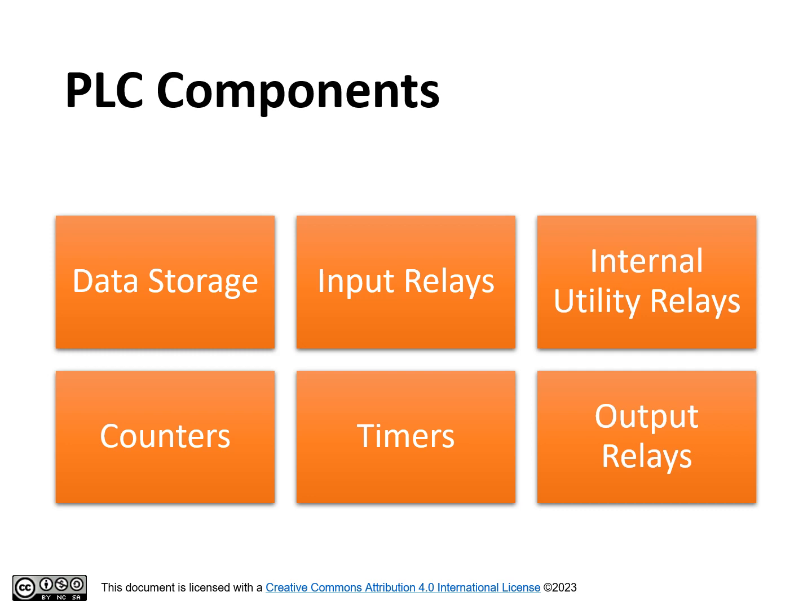Timers. These logical components come in a variety of types. They can be on delay, off delay, retentive, and non-retentive types. Timing can also be of varying granularity from millisecond to a second.